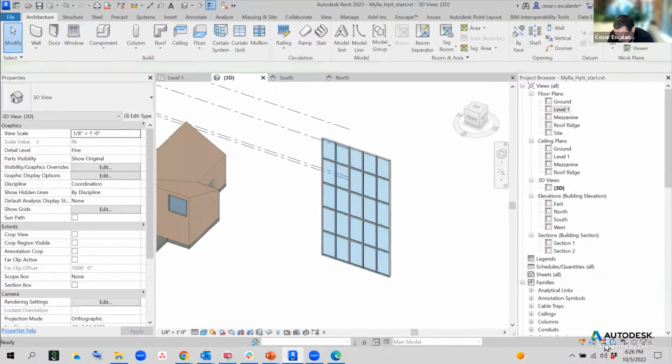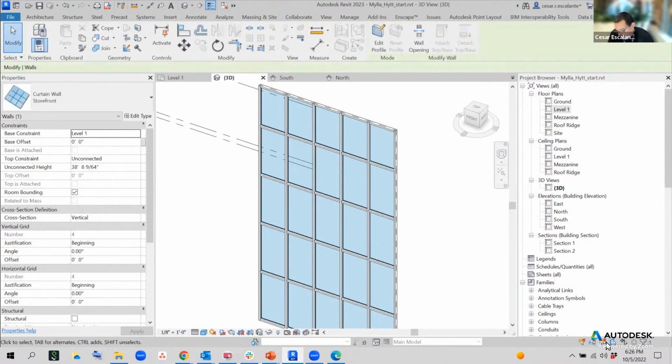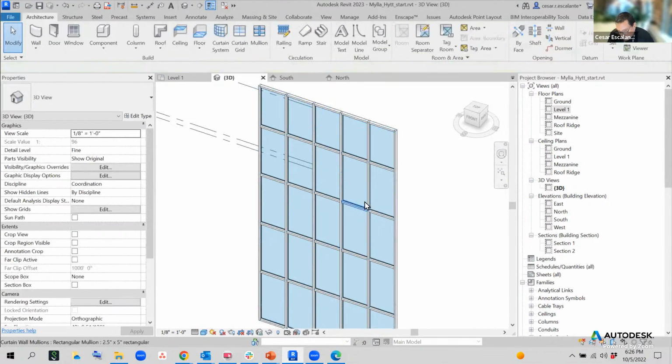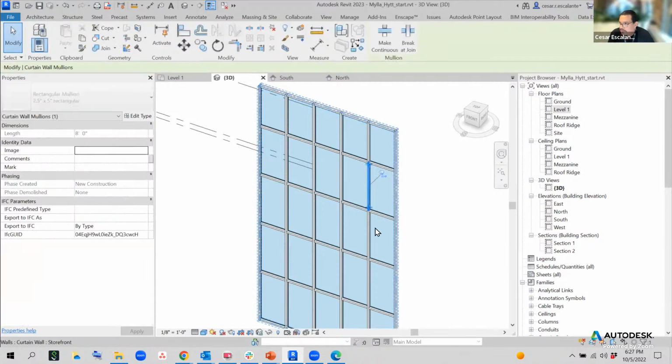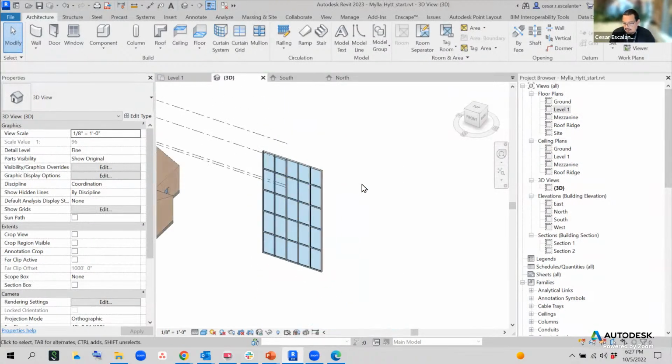If this has a little X, you won't be able to select anything that is pinned. But if you disable it, then you will be able to select. This is like a foolproof restriction. Sometimes it's used to prevent users from picking things like grids or levels that are pinned, so no one's moved them.